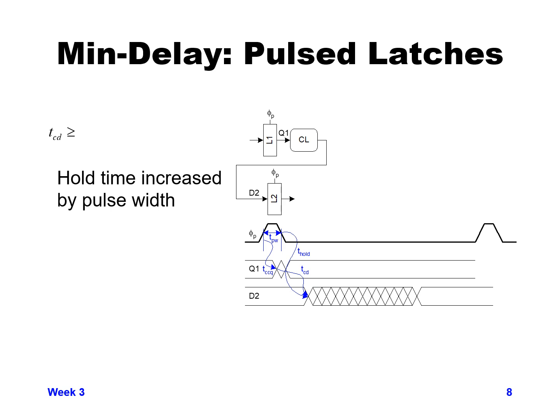So when we start comparing the closing edge of the latch, or the closing falling edge of the clock, T hold time, to the data propagation delay earliest D2 time, you can see that you could start potentially running into a problem there.